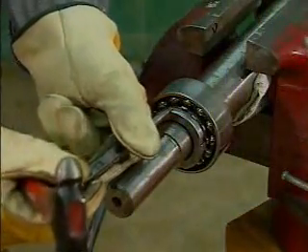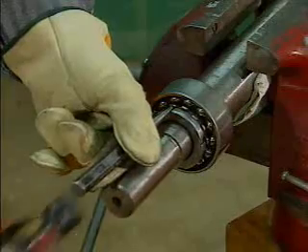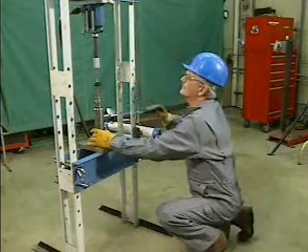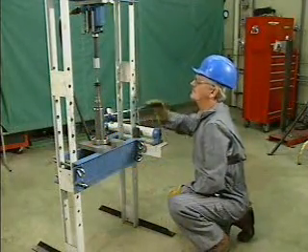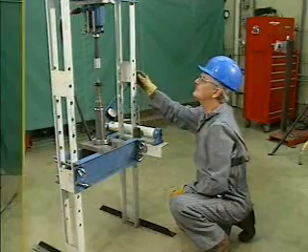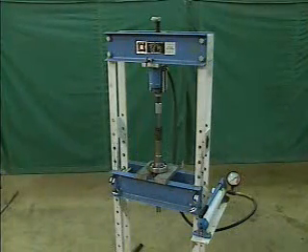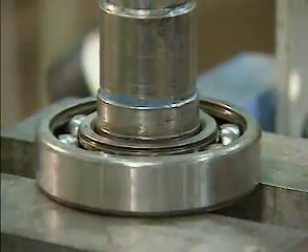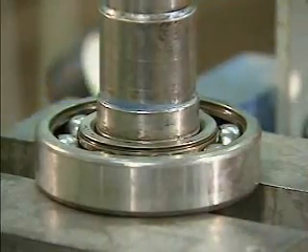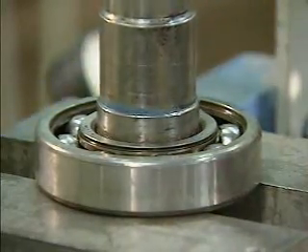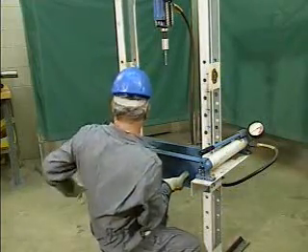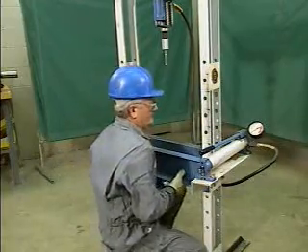In this part, we'll look at two methods for removing the press fit inner ring of a bearing from a shaft. The first method is used when the shaft can be removed from the machine. This method uses a device called a hydraulic press. A hydraulic press is a machine that is frequently used to apply pressure to the parts of a piece of equipment that is being assembled or disassembled. A hydraulic press removes a bearing from a shaft by holding the bearing in place and pushing the shaft through the bearing. Let's watch a mechanic use a hydraulic press to remove a bearing from a shaft.